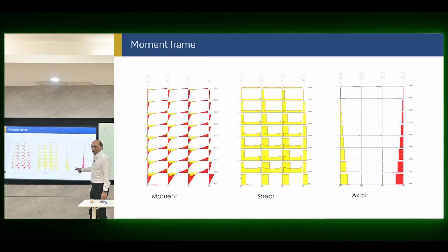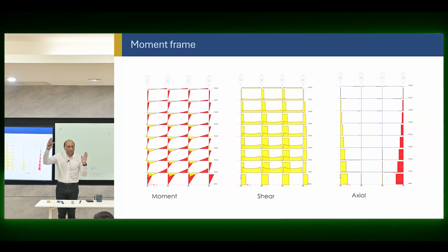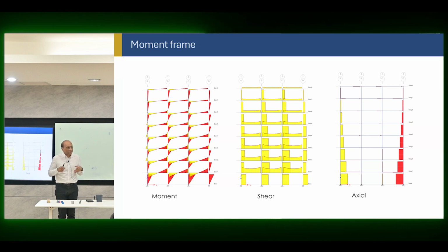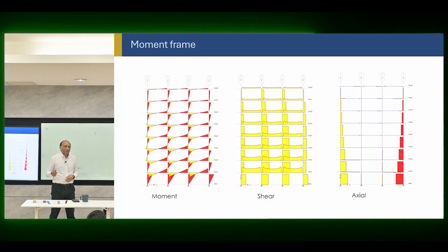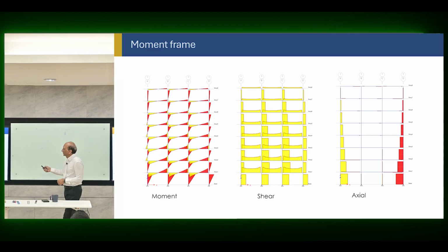You can see from here now the important thing. Axial force is only on the outer columns. That means they are really the ones providing that couple for resisting things. The interior columns are not really efficient in axial force. So one of the rules was it must be axial, which means interior columns are not helping you much. That's why we can make them gravity columns also, right? Okay, so that's the basic idea of that.